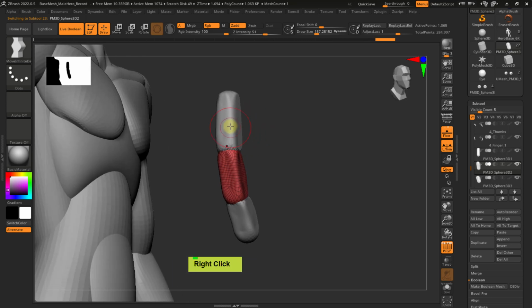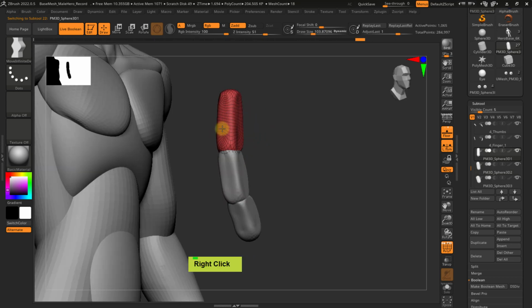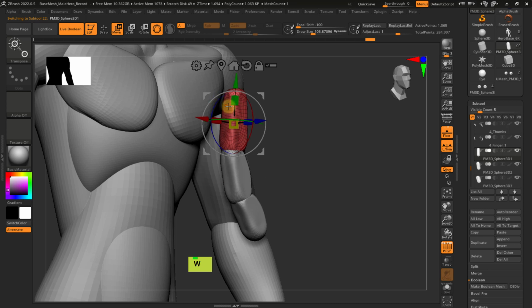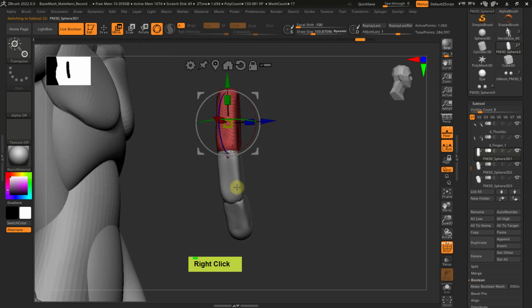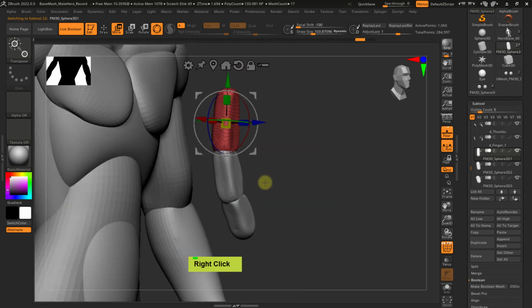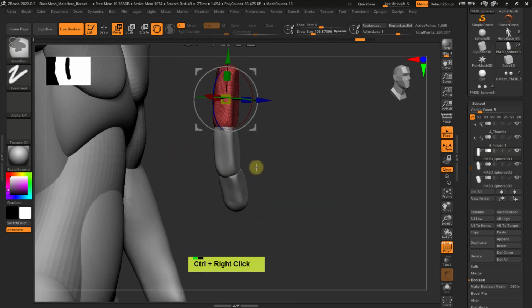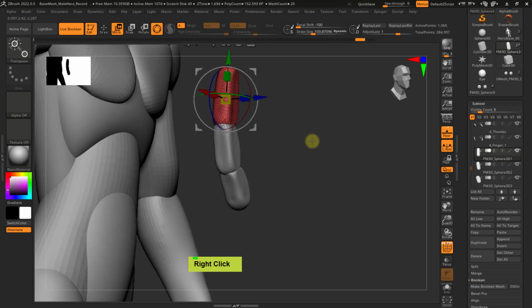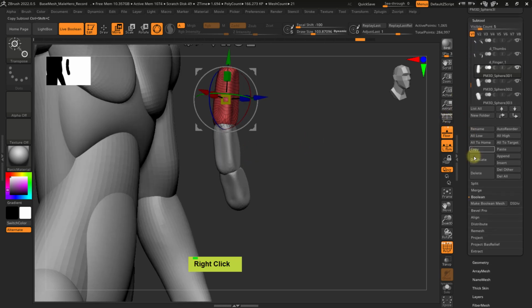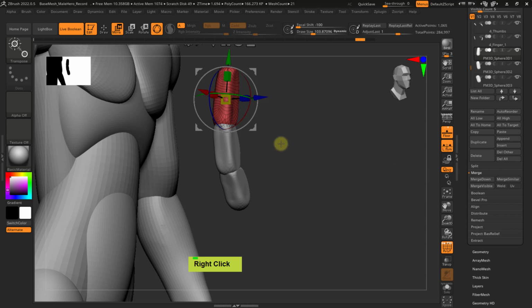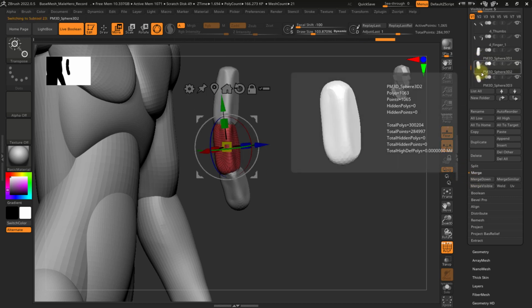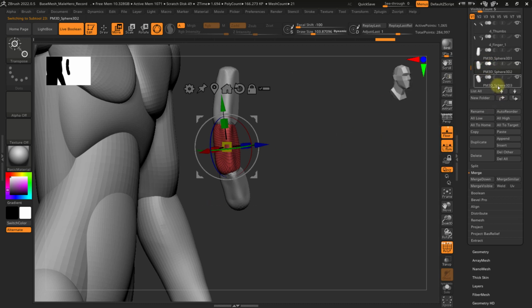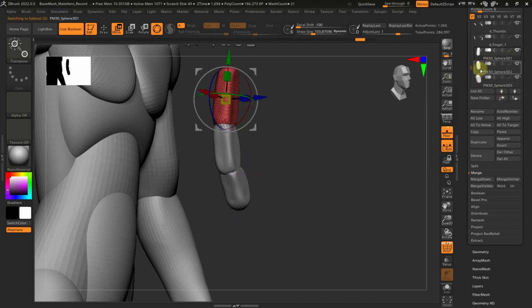So you can do it, and it's not that bad if you are just trying to manipulate and fix things. But once you have a basic layout and the angles are okay and the proportions are okay, then you want to handle them as one unit. So here we have a function called merge. Merge will actually not weld, but kind of join the models. So if I'm hitting merge down, it will merge this one with the bottom, and the bottom happens to be the next part, and then the other one happened to be the next part. So that also works fine.